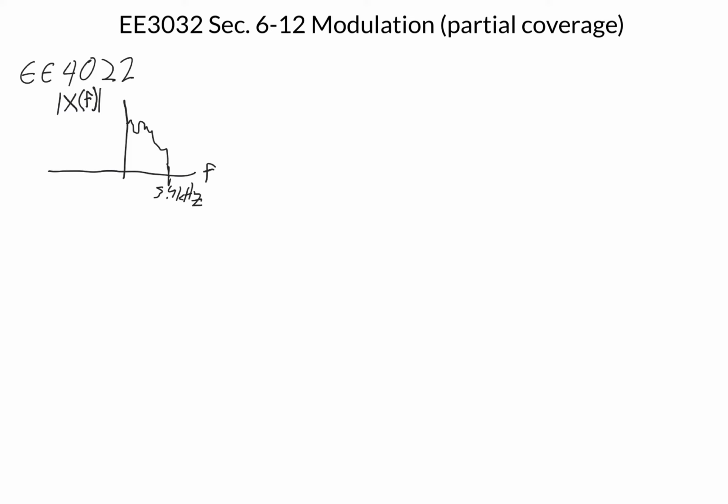Now, since our audio signal for our example here, and most signals of interest that we want to transmit, are real valued signals, we know that the Fourier transform has conjugate symmetry. So that means that the magnitude Fourier spectrum is going to have even symmetry. We have the same magnitude at positive and negative frequencies. So here we draw this to look like a mirror image. And let's call this voice number 1. And then there's also a phase spectrum, but we're not drawing that here.